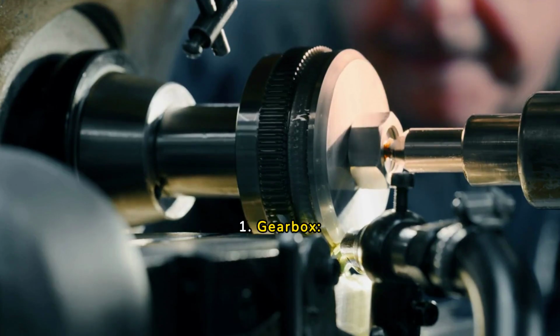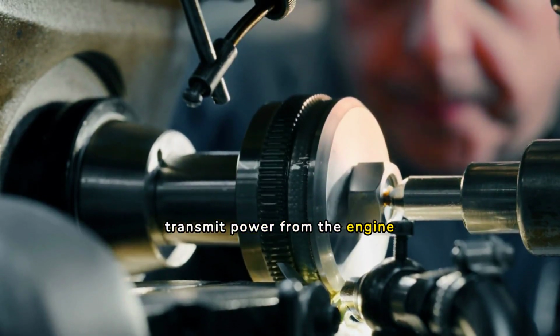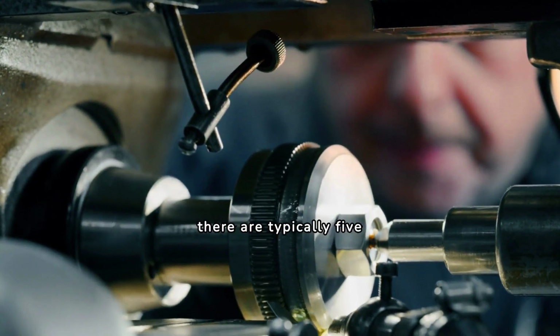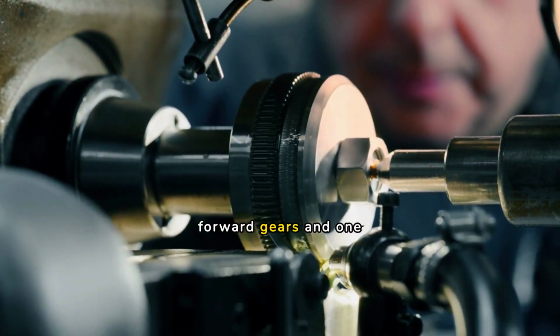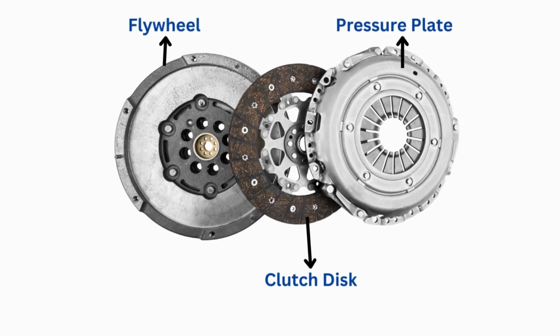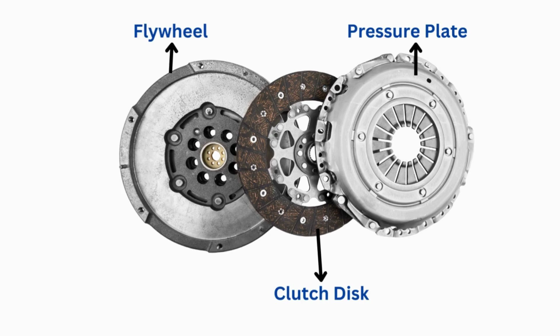1. Gearbox. The gearbox contains the gears that transmit power from the engine to the wheels. In a 5-speed manual transmission, there are typically 5 forward gears and 1 reverse gear. 2. Clutch. The clutch connects and disconnects the engine from the transmission. When the clutch pedal is depressed, the clutch disengages, allowing the driver to change gears. When the clutch pedal is released, the clutch engages, transmitting power from the engine to the transmission.